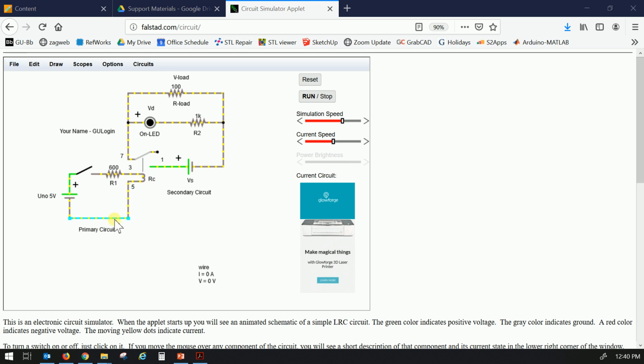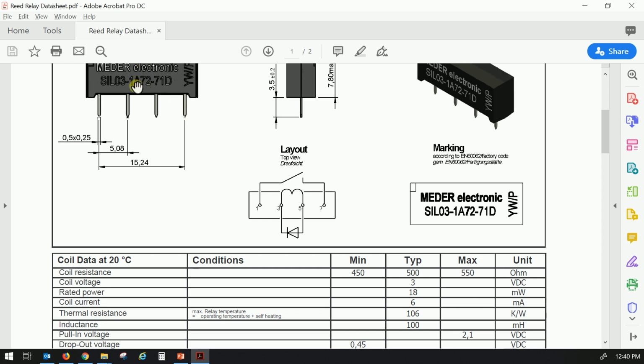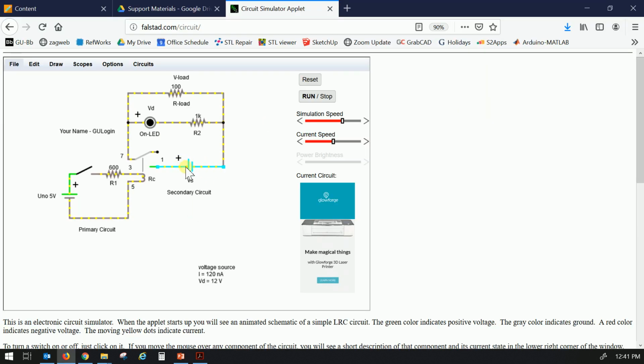So again, that's how we want to do the wiring for that piece. Let's take a look at the other pins. Pins 1 and 7, or in this case, the far left and the far right when you're facing the label. And that will be important to make sure the label's facing you as we make these observations. Current will pass in on pin 1 through the switch and then out on pin 7. And so let's take a quick look at that. We've got the secondary voltage providing power to pin 1.